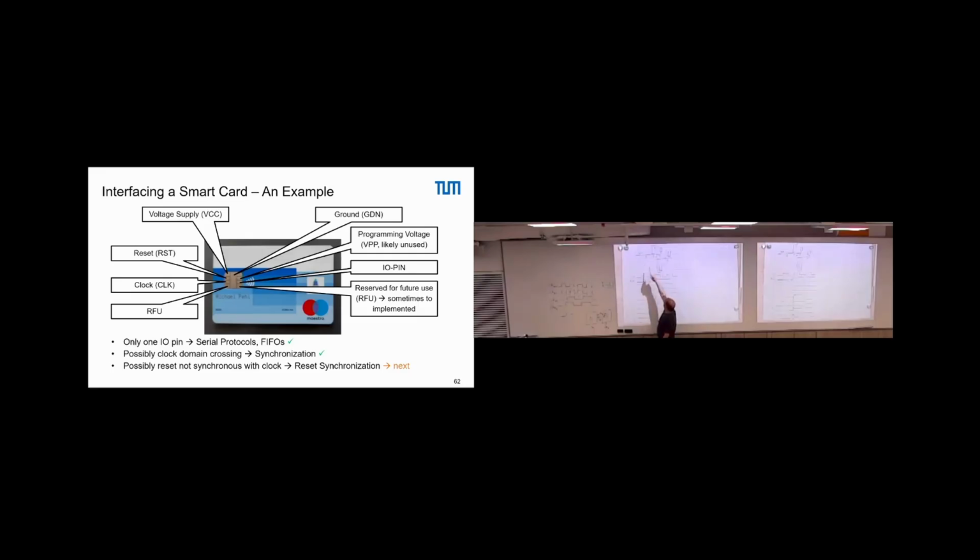Okay? The first one, the upper one, where the flip-flop is out of our picture, we have two capacitors. So we have a short delay, which is this one. Then it follows this signal. It's not dependent on the clock. It just goes up and stays high. The other two have 1, 2, 3, 4 capacitors. So we have a larger delay. So it is delayed further than this one.